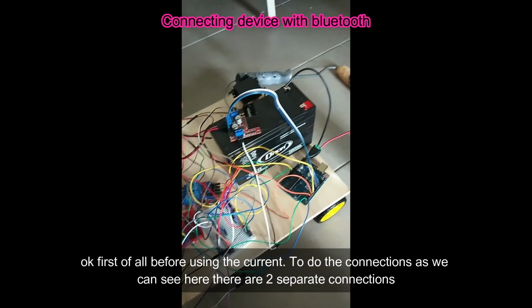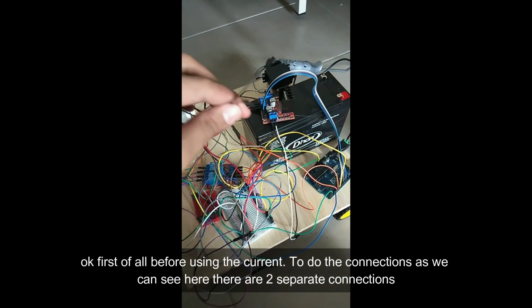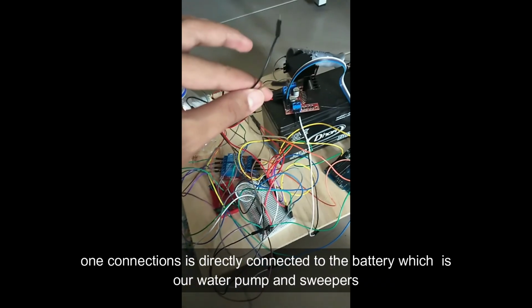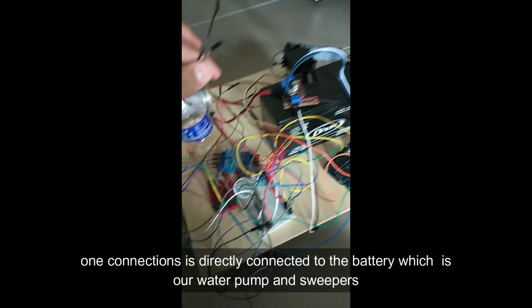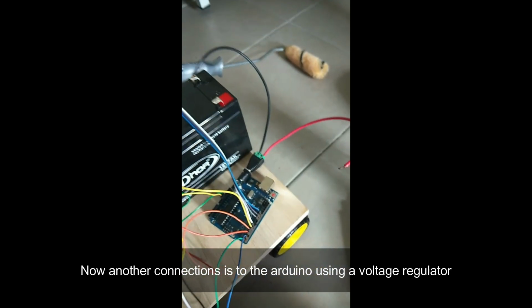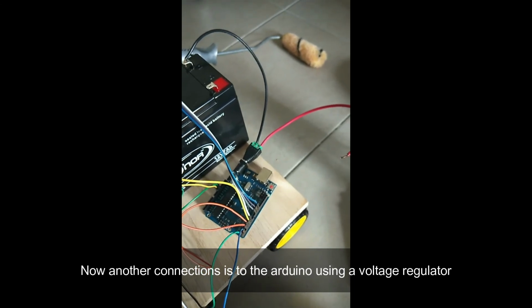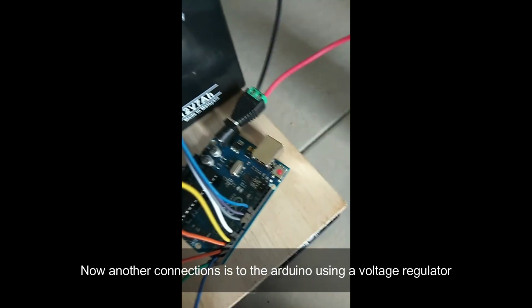Okay, first of all, before we use the current, we do the connections. As we can see here, we have two separate connections. One connection is connected directly to the battery, which powers our motors and our fibers. The other power source is connected to the Arduino, as it supplies power to the Arduino with the voltage regulator.